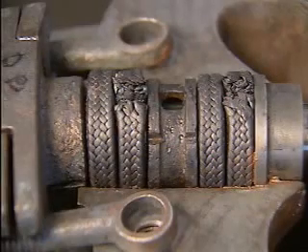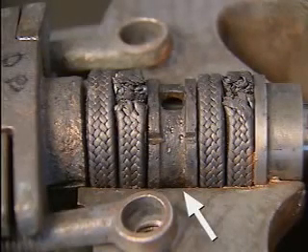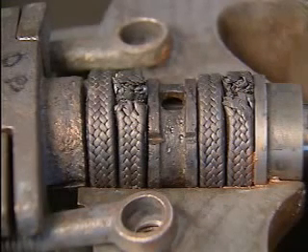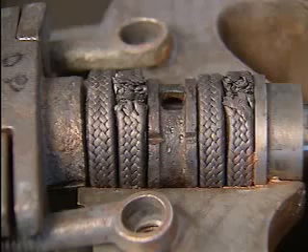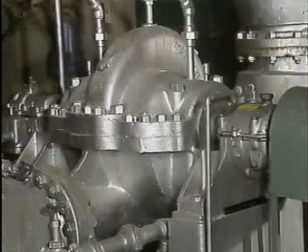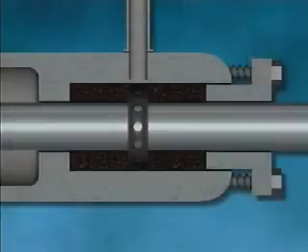On this pump, a metal ring called a lantern ring is installed between two of the rings of packing. The lantern ring provides a means for bringing more liquid into the stuffing box to help cool the packing. Certain applications, such as pumps, generate more friction than others and require this additional fluid to keep the heat that builds up under control.